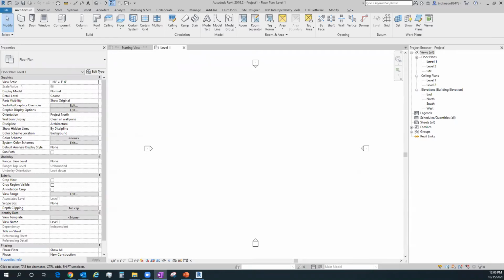And is it global? Do we need to solve it for everybody, or do we just need to solve it on this machine? If it's just this machine only, chances are you can reopen your file by clearing the file and the backup file from your local drive. And then once you reopen it from Central, you get a fresh new copy and everything is running fine again. That's a great scenario to have happen because it's a super easy fix, right? Just reopen after you've deleted your files. In that case, no harm, no foul.